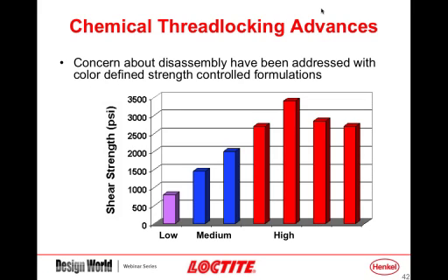There are the high strength red products, which are designed for permanent assembly. But when we do say permanent, you can use heat to soften the thermoset plastic and then still disassemble the system. It's just that in most situations, this red will prevent fasteners from being disassembled, and you use them selectively, like a stud into a housing. And then we also do have low-strength products, which are typically designed for screw applications, where you may have a long thread engagement and a relatively low-strength fastener, and that would be where you would use a low-strength product.